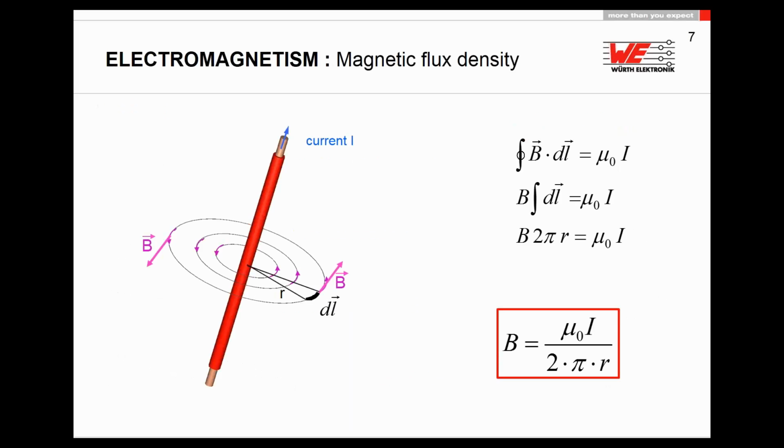The most important thing when you are powering a copper wire is to remember the right-hand rule for the direction in which your current is flowing. If you point your thumb in the direction of the current and put your forefinger above the wire, you will have a magnetic field. This magnetic field is directly proportional to the current and inversely proportional to the distance.